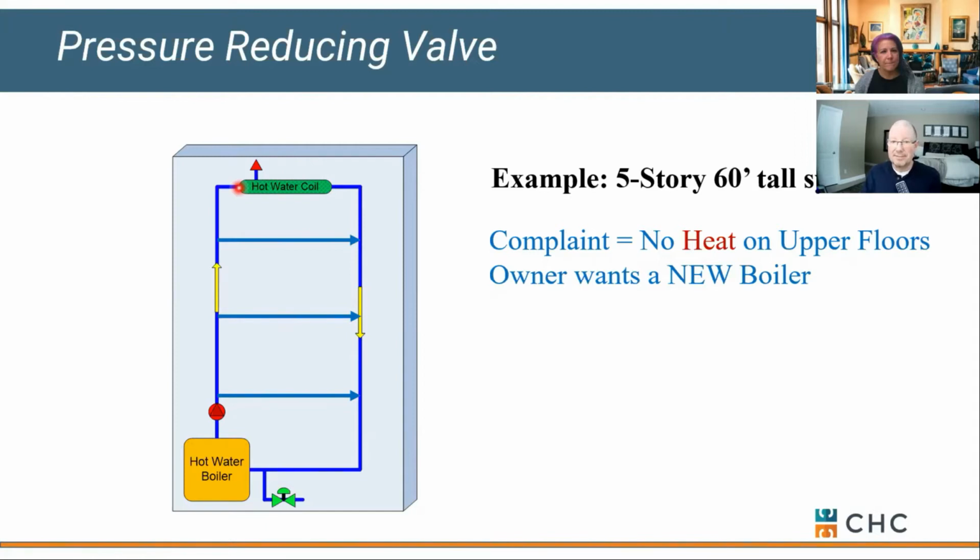Not necessarily. Our salesman walks in, he sees, hey, we've got what seems like a really nice boiler for this size building. Let me ask you a stupid question. What's your fill valve set for? Anybody want to take a guess? 12 pounds. When it comes out of the box and you don't adjust it, guess what happens? You fill your system half full of water.